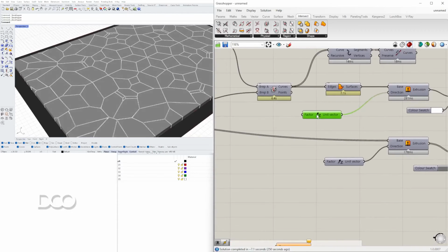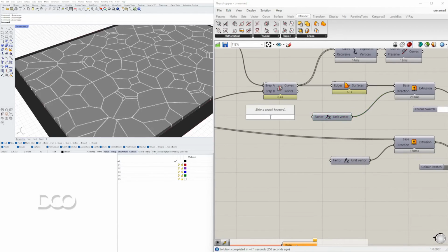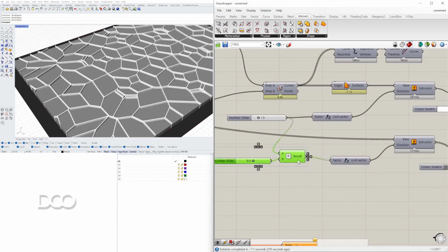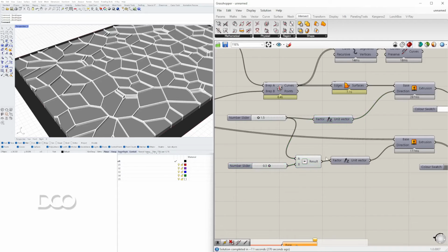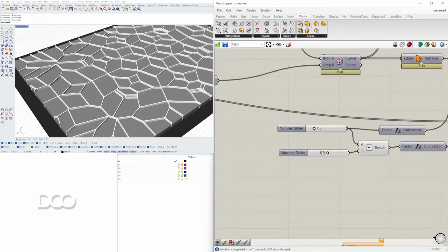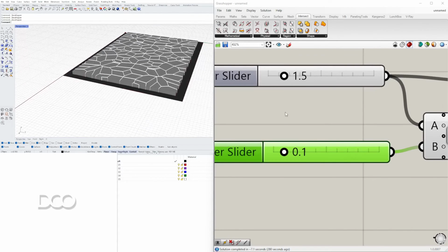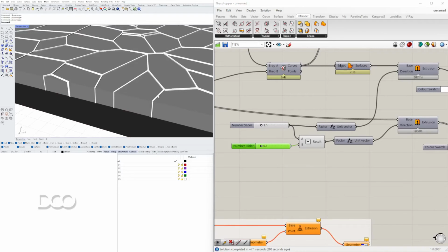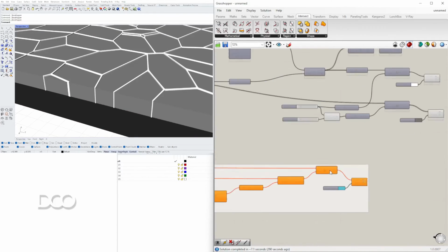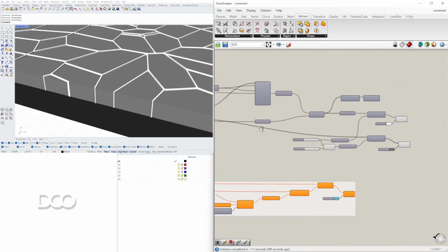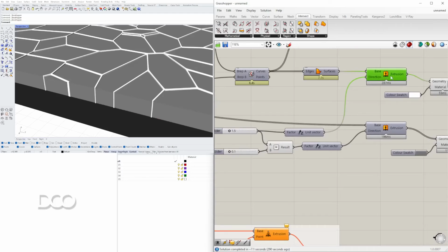So as long as we extrude this one out a little bit more, so we'll say this would be 1.5, and then we'll do minus 0.5 for this one. And if we want the difference between the two to not be so much, well, then we go 0.1. And if that's the grout thickness, well, then we'll make the extrusion for the outer band the same as for